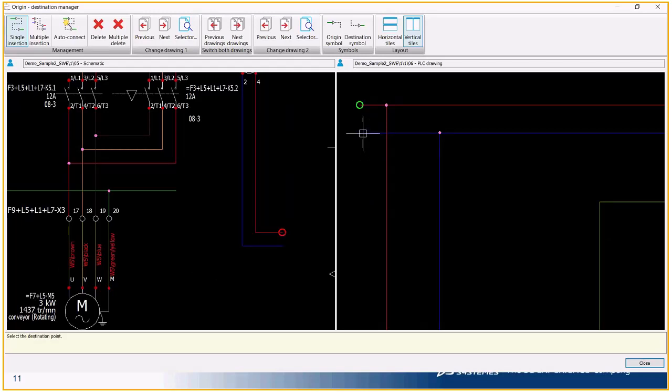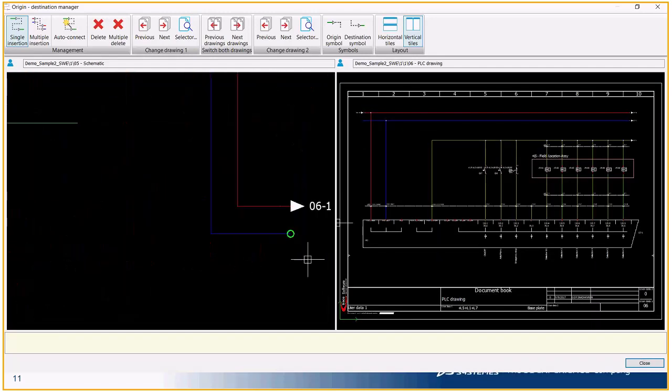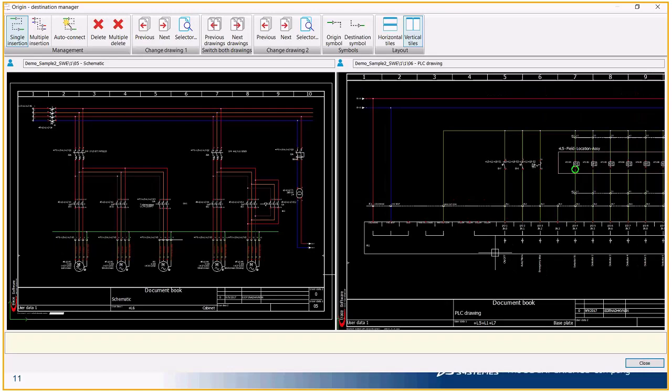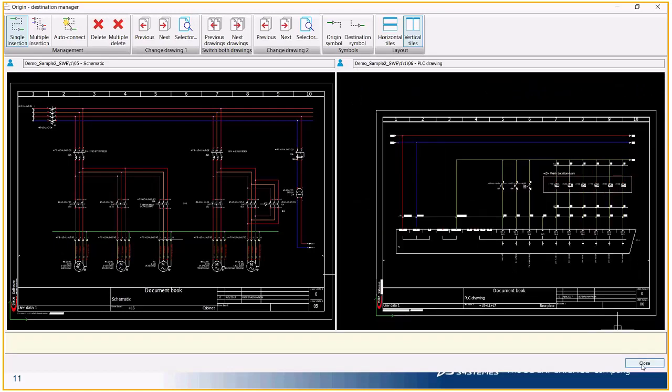Even if I take my cursor to the green, it won't be able to connect, because it actually catches the equipotential point or voltage which is being used. We know that the transformer, when it is phase and neutral, the 24 volts AC phase will be connecting only with the phase. That kind of automation is an advantage of SOLIDWORKS Electrical. Let me collect this. Now I'll be connecting the blue, that is the neutral point, with the other neutral point as a supply to the PLC in the other page.